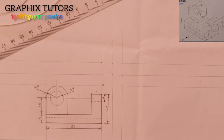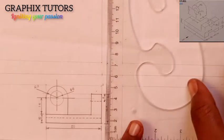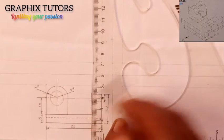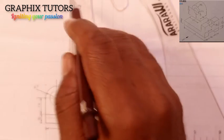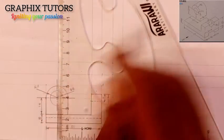Now the next thing you need to understand is that in third angle, the plan is always on top of the elevation. That's one point you need to know, right? While in first angle, the plan is always below the elevation. So what will I do? I'm going to project these points up this way, this to this. All those points I have, I'll project them this way. I need to draw the plan I have here also, and here.